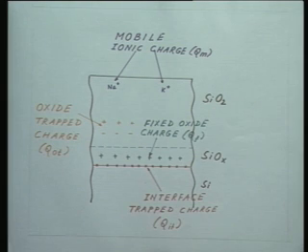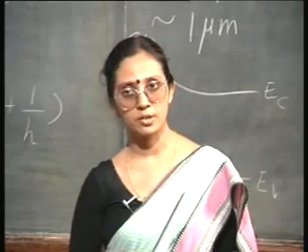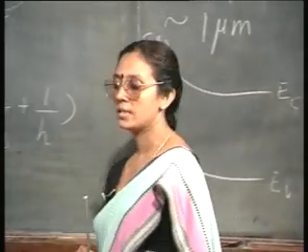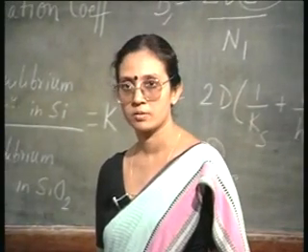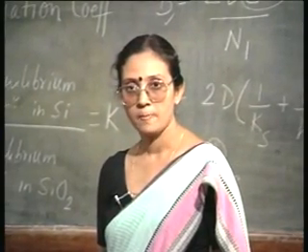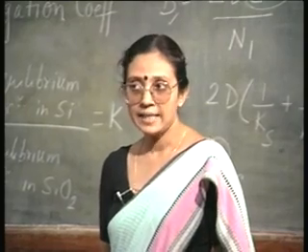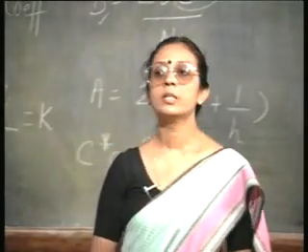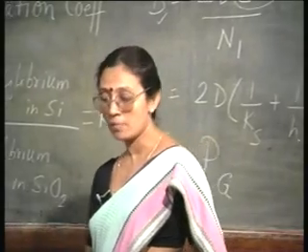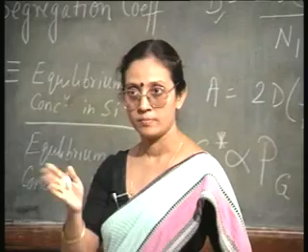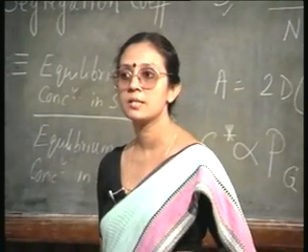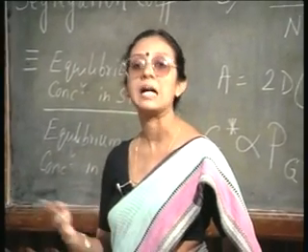That is because in silicon thermal oxidation, these charges are mostly always only positive charges. And they come about because of incomplete oxidation. Again remember, thermal oxidation is taking place inwards. That is, the interface is the region which has oxidized the last.